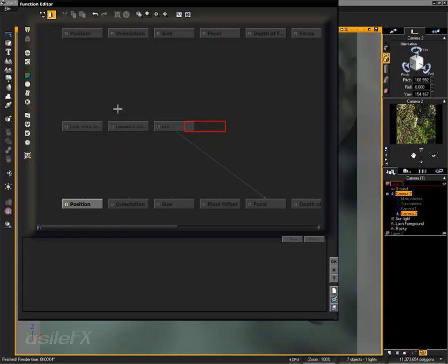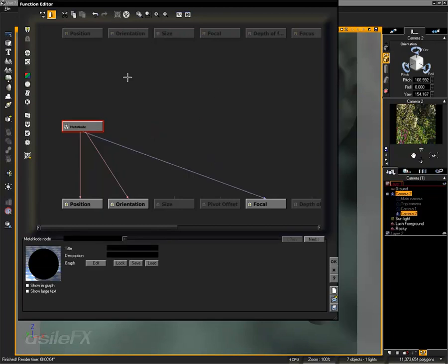So the easiest way to really get this into another file, another step along the way, is just copy all of these nodes. And first what I want to do is connect the position and orientation. By making these connections ahead of time, instead of doing it within the metanode, we don't have to add any additional nodes. They'll automatically be created because the links are already there. So we can select these 3 nodes and just click Metanode. And this is for version 7 and up. If you're using version 6 or 5, you will just need to copy over that data. And the internal unit wasn't added until version 7, so you really wouldn't need to worry about it anyway.